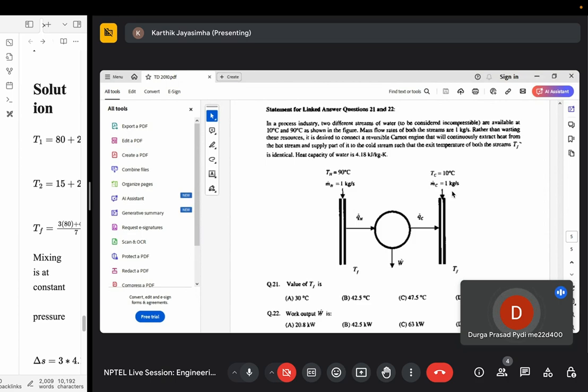Okay, first thing, did you understand your mistake? Yes, QH should not be equal to QC. That is the first part. Now the second part is, if QH is not equal to QC, you need to find a relation between them, and that comes from the process inequality. So just see what we have just derived. It will be mCp ln(Tf by TH), the same as whatever we derived just now. Try that once.